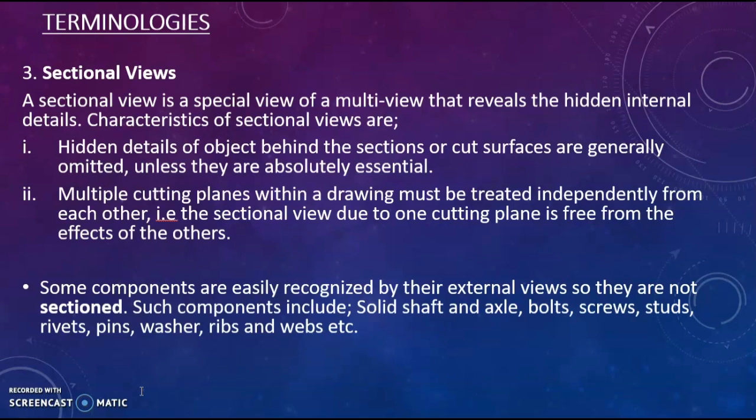Sectional views. What do we mean by a sectional view? The sectional view is a special view that reveals the hidden internal details of the sectioned object. After you've sectioned the object, the view we are seeing, we have many types of it. It's a very special view that reveals these hidden details of the object we've sectioned. Let's look at some characteristics of sectional views.